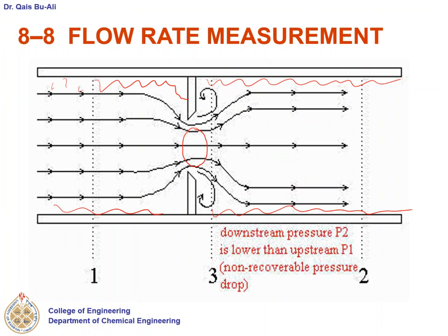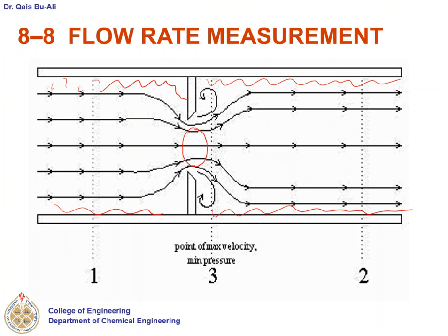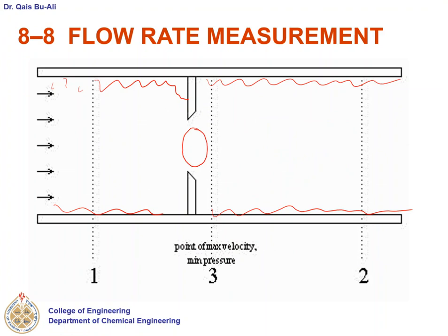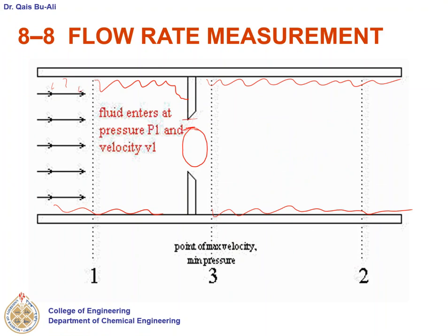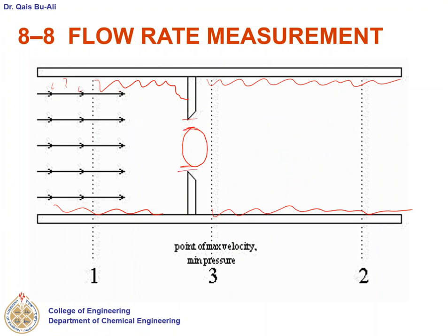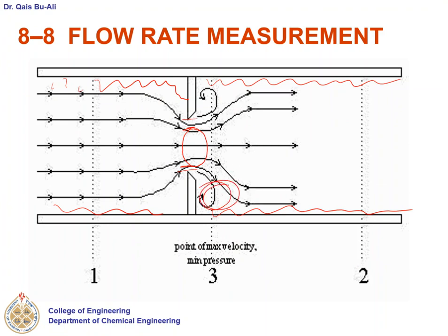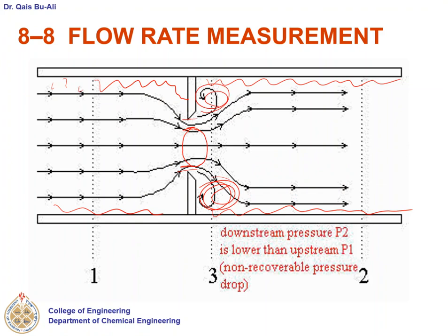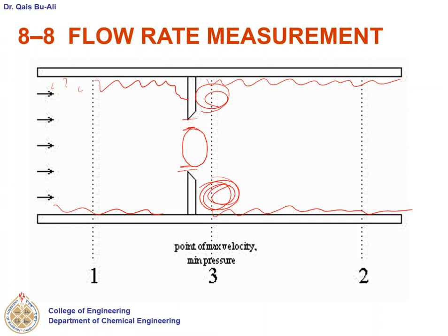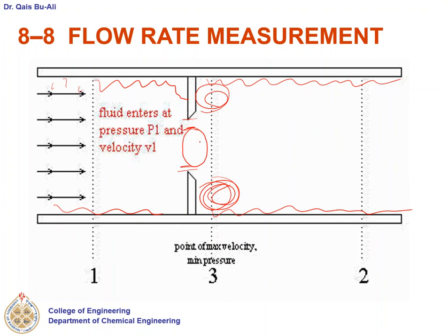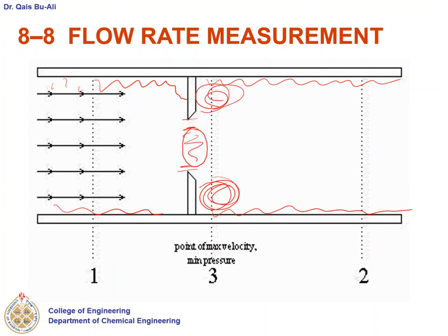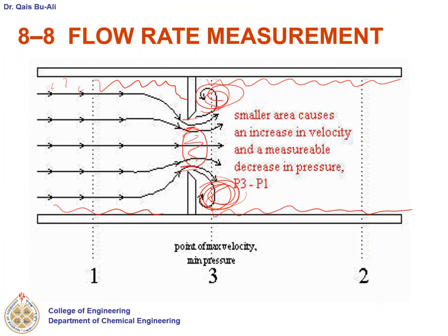I talked about this before, if you remember. We said it's a place where the fluid cannot utilize the whole diameter. I am just utilizing part of it, and this will cause also losses. And also I have those eddies. So now I have three types of losses: friction with the walls, vena contracta, and eddies that are happening here. All of those will add together to have a lot of losses.